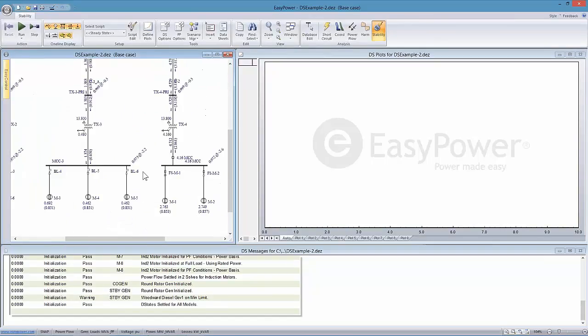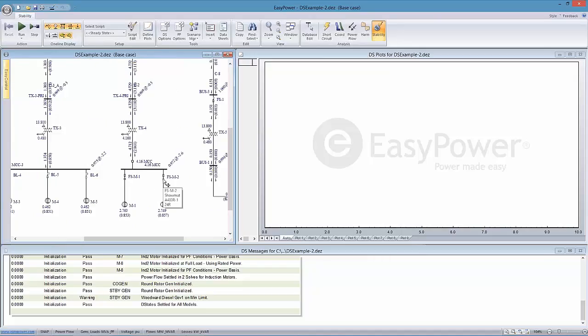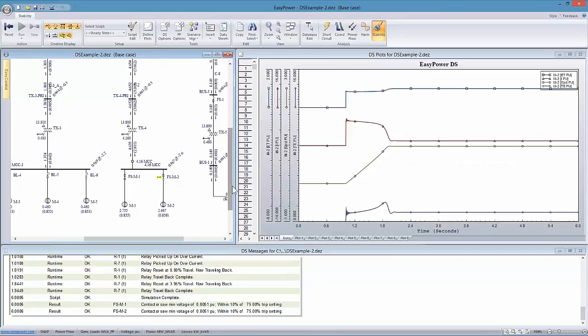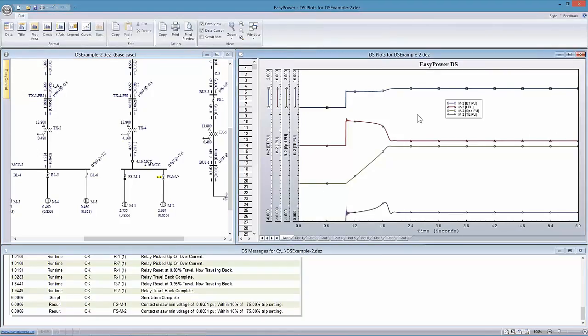As I mentioned earlier, we have the ability to double-click on a system. So here's a fairly large load. Let's open and resolve, and then double-click on this. As I do that, I've started this motor, and the tools automatically know that what I'm looking at is a motor. So my display is showing the motor voltage, motor current, motor speed, and then the torque that's being generated by the motor. And this gives us a pretty good idea of the response of that motor.